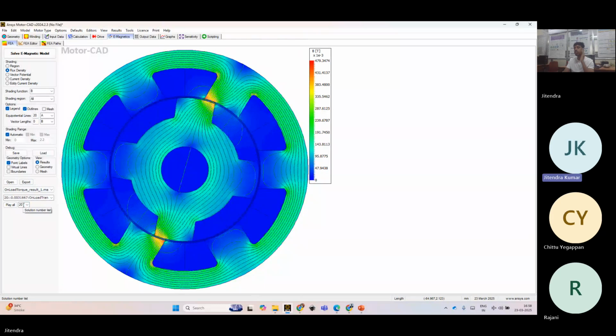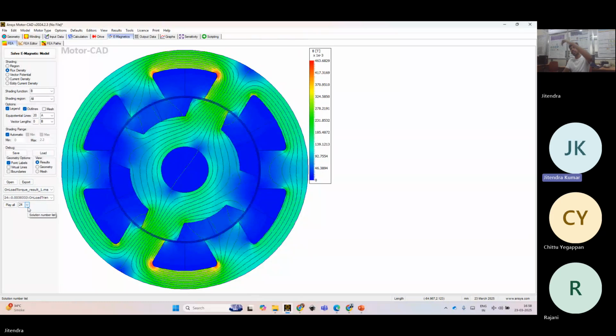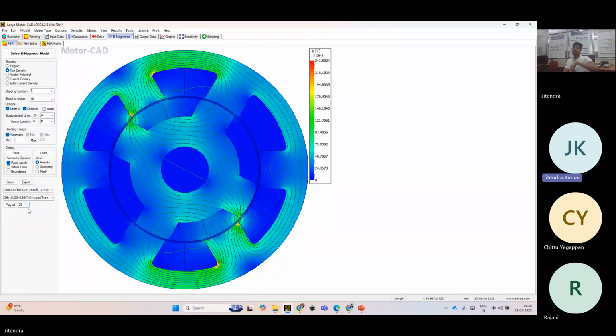Further the rotor will start rotating, and flux linkage will increase, right? It will keep increasing, become maximum here, and then start reducing and go to the off position. Then again phase A will turn on. Okay. I hope you got the idea behind it.